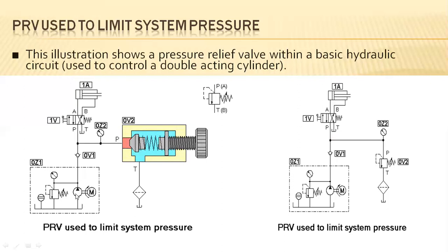The motor will pump the fluid with 4 bar of pressure, and the entering pressure will be measured here by the pressure gauge, and 1 bar of pressure will be released to the oil tank. So 3 bar of pressure will be entering the system inlet condition.